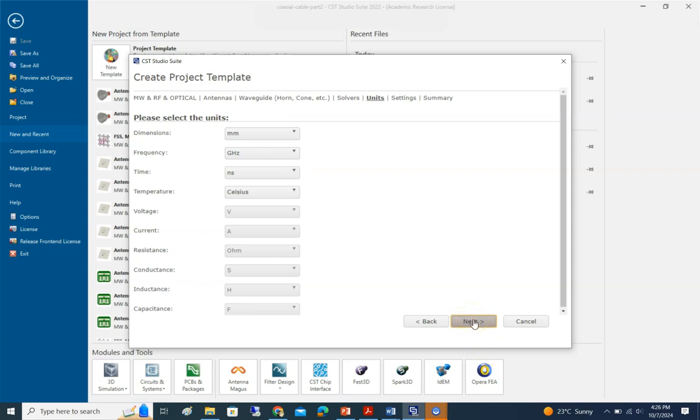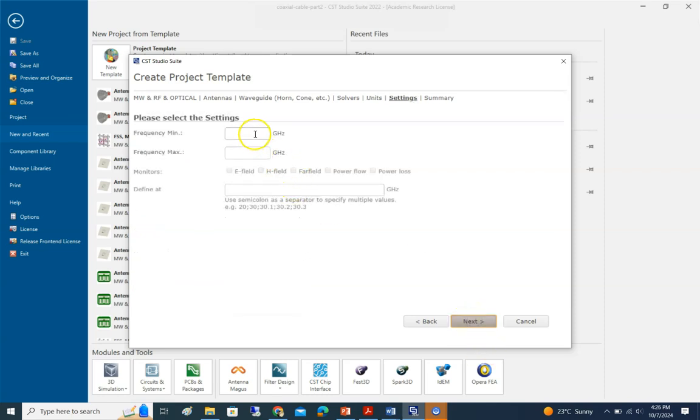We'll not change anything here. This is pretty handy. Rather than changing it later, changing it here is better, so that you don't have to go to those setups again before you run the simulation. So it's the range, which is 0.5 to 2.5 gigahertz. This is a good habit, to check on those things just in case.